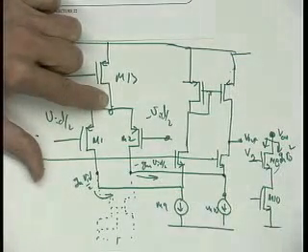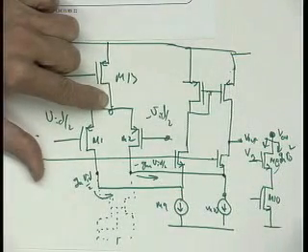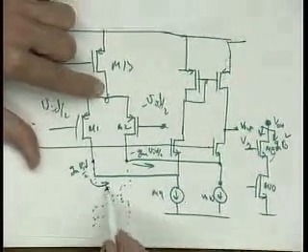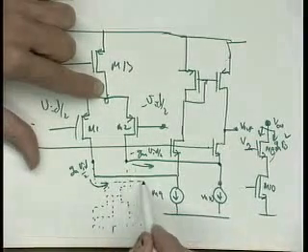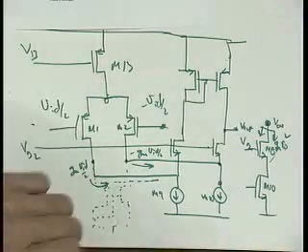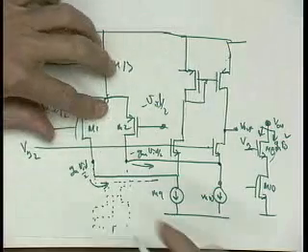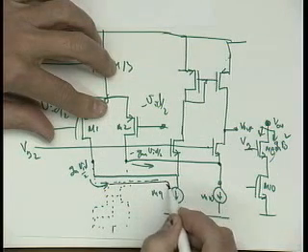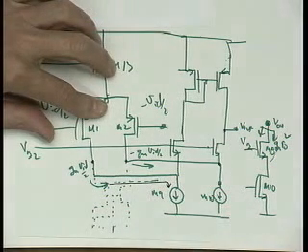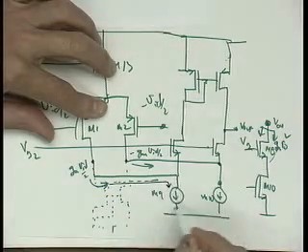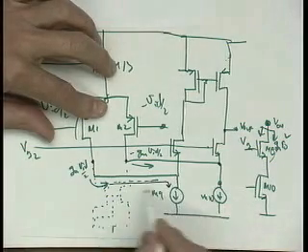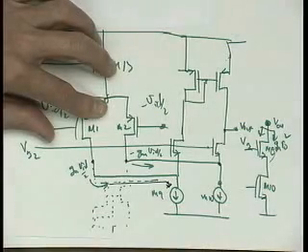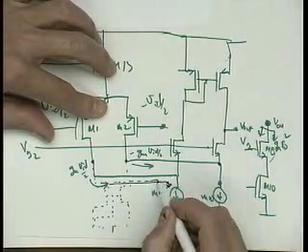Now, where does that current go? Here's the folding. Let's follow this little juice of current here. It goes cruising along here. Let me change colors. Okay, so here we go. So we come zipping along here. Can we go down in this direction? This is a current source. If it was an ideal current source, no small signal current can go into this current source. So it can't go that way. So where can it go? It's got to go up.